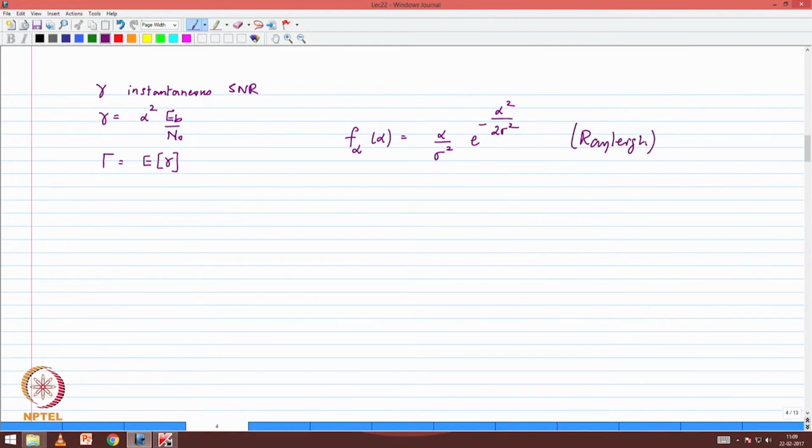The envelope is Rayleigh distributed. The SNR PDF f(gamma) is given by 1 by uppercase gamma, e power minus gamma by gamma, where gamma is equal to, oh, I've already written that. Okay, so this is the exponential PDF. The other parts that we had also revised or derived in the process was the bit error rate